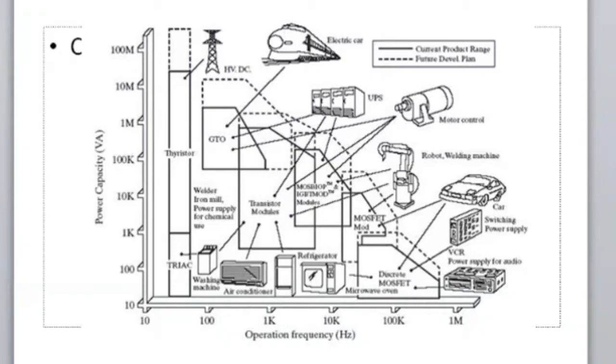And again, power. How do you calculate the power? With this torque calculation, you will not end; you will calculate the power also. Power equals 2 pi nT by 60, right? Here in the case of the fan load also, output power is equal to 2 pi nT by 60, which means power is proportional to torque into speed.